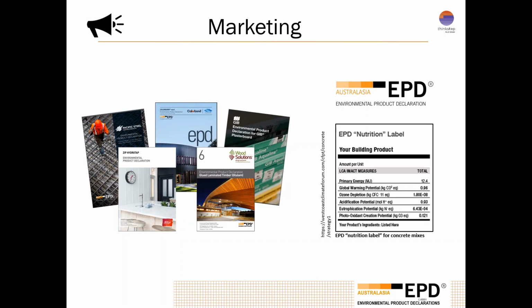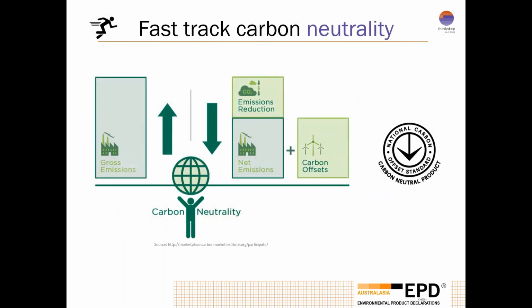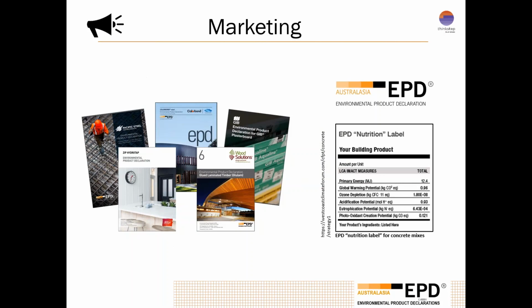When you're thinking about what an EPD is, one way of imagining the information that's presented is a comparison to a nutrition label. So if you flick over the back of a product and you see the grams of fat and the kilojoules of energy and whatever else in it, an EPD is similar to that, but it's giving information on the carbon footprint, the carbon embodied in the product, or the energy embodied in the product, the water embodied in the product, contribution to acid rain, to nutrient loading in waterways, to summer smog, all these different things. So an EPD is kind of like a nutrition label for a product, but covering the full life cycle or a subset of it.